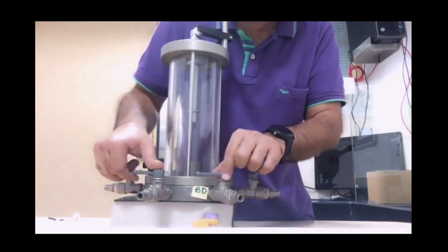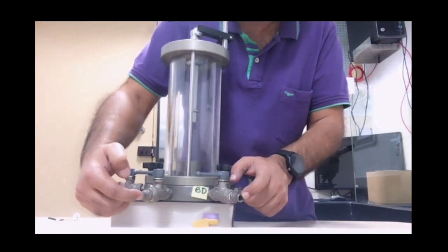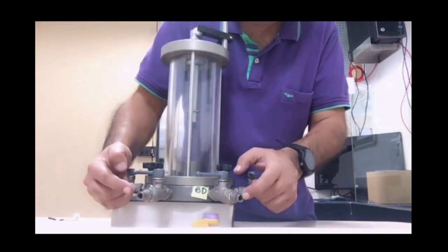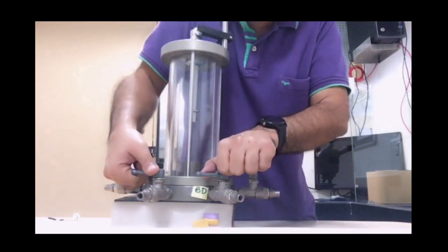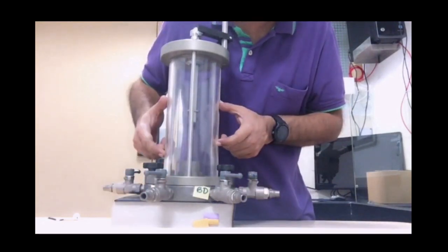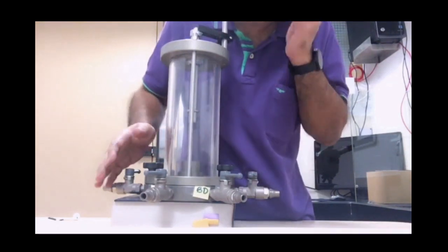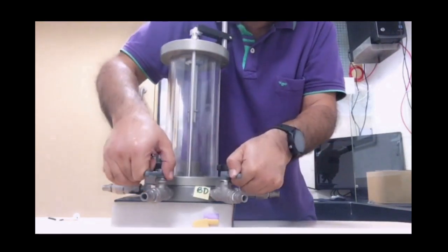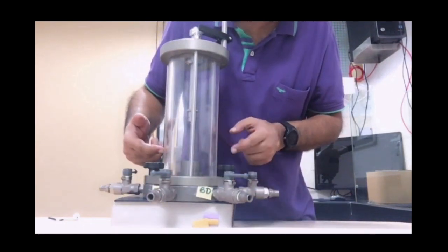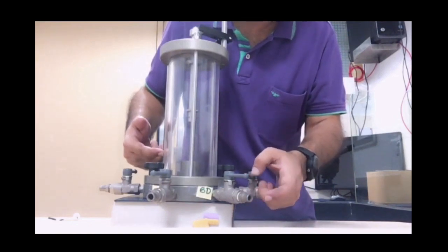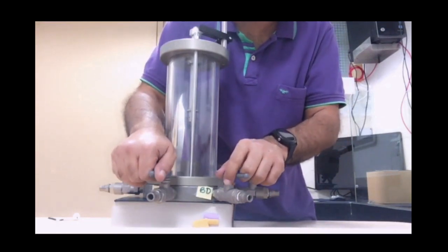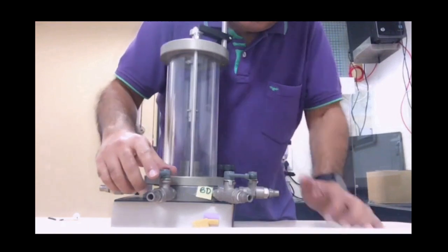So one way out is, my cell pressure is at a certain value, which is maybe about 5 or 10 kPa higher than this. So one way out is, I open these two valves together so that the chance of the sample getting exploded is minimum. You will find that this opening is a trick. If I just lose a fraction of a second, I may end up destroying the sample, because this fellow over here can go faster if my opening of this valve is not synchronized with the other valve.